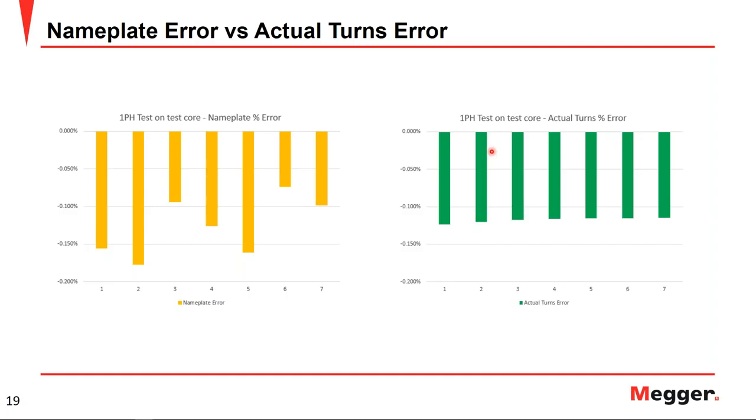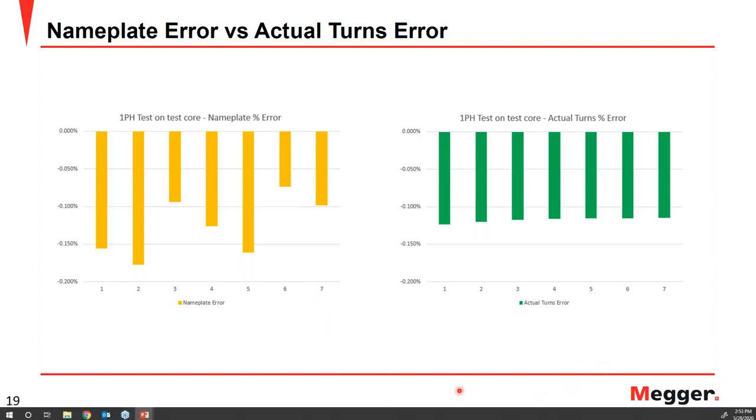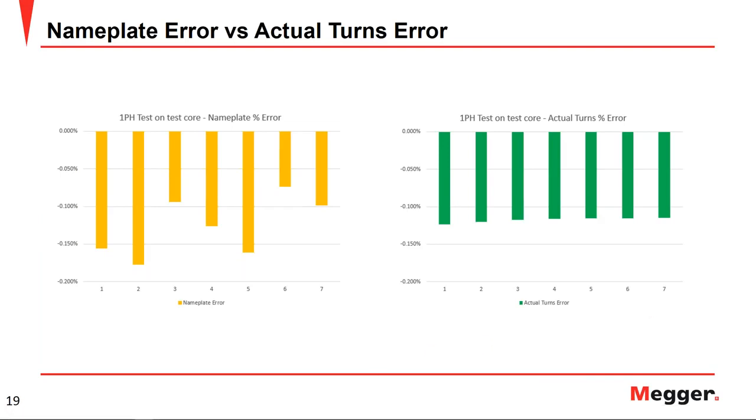All right. Dinesh, is there any relation between rated voltage and excitation voltage for testing? Before I answer that, I'm really glad to see these questions coming up, because these are the questions coming from people who have experienced these things in the field. So just think about what is happening when you're doing the excitation test. You are basically doing an open circuit test, applying a voltage to the primary side or the high voltage winding, and recording the excitation current.